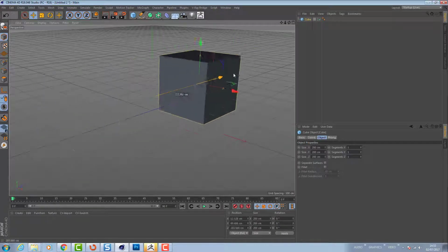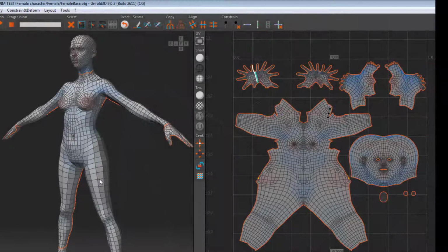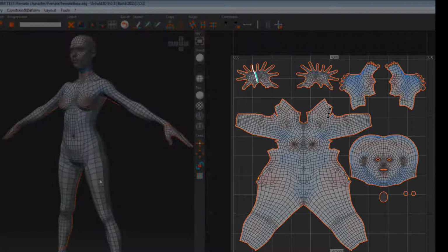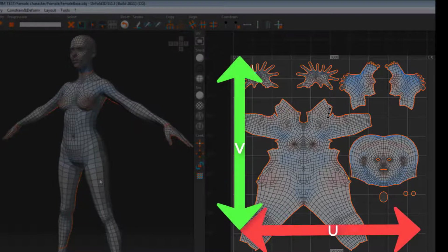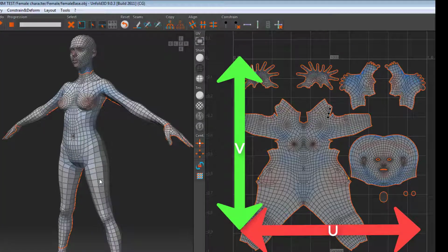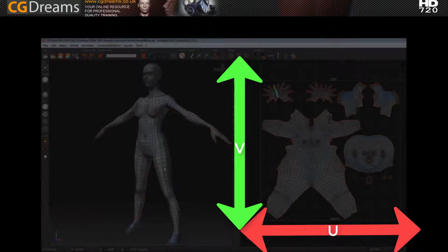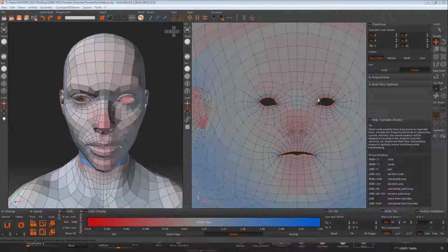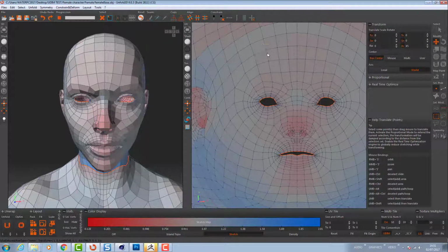When we are dealing with the UV coordinate system, the two letters in our particular case are called U and V. The U stands for the horizontal position and the V for the vertical. We give the UV the added term map because it is a map which helps us and the 3D software to know what location each point of our 3D model is located in our UV space. Hence we link the 2D world to the 3D world.